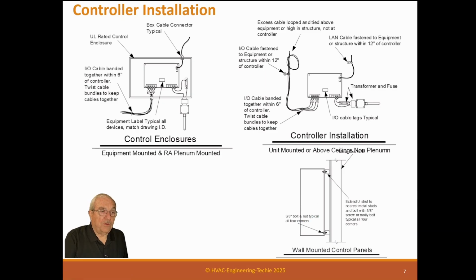And also you have to be real critical to look at the back of the panel. Because most panels, 3R panels that are rain drip, have holes in the back of the panel, which means they're now violated. To do that, you have to have a solid plate back here to mount this on, so that solid plate prevents those holes from being open to weather. That's an experience kind of thing you've got to check about. So, these are mounted exterior. If you mount them on a wall, no problem, because those holes are sealed. But if you mount them like this on a piece of structural steel, like under a cooling tower or something, you've got to seal that back up, and normally you just use a plate on the back to do that.